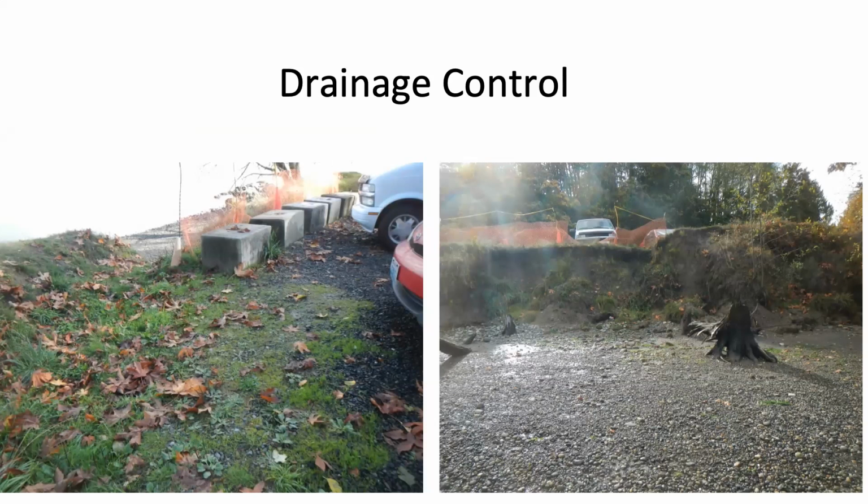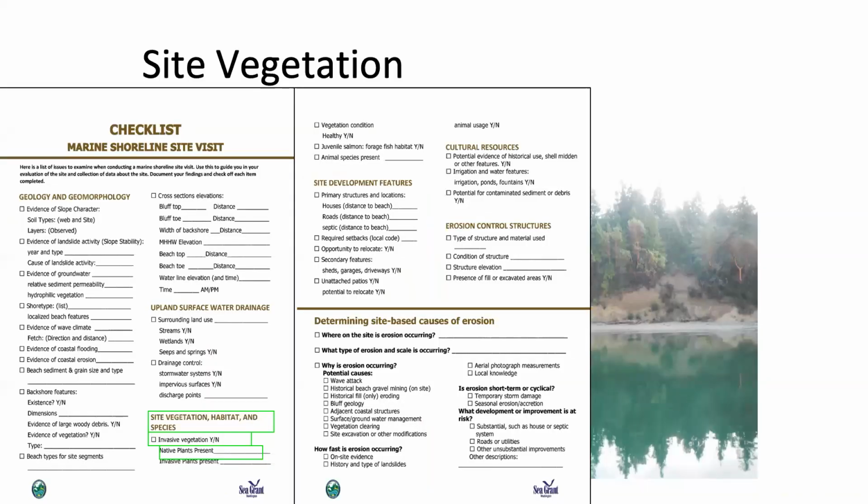So next on the list, we come to vegetation. It may or may not be able to help prevent large-scale mass wasting or landslides. It does function to help stabilize the slope in the interim, particularly on the timescales that we're dealing with on a lot of these mostly residential type sites. So the best vegetated slope has a broad range of vegetation types, from grasses and ground cover that can function to break up the momentum and energy of falling or flowing water, to brush that provides more of that surface level shear support, all the way up to large trees that have a little bit deeper roots to intersect failure planes, as well as aspirating moisture right up out of the slope.